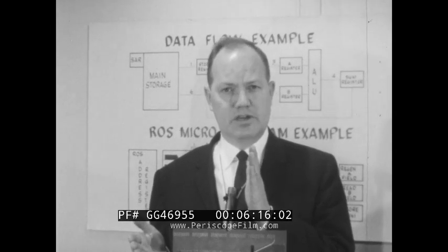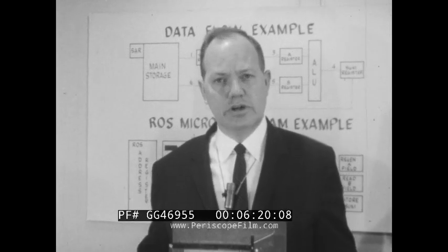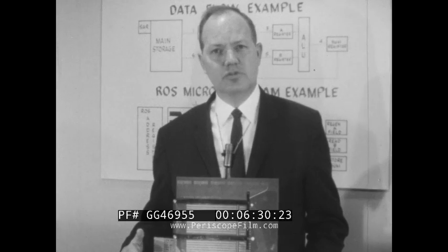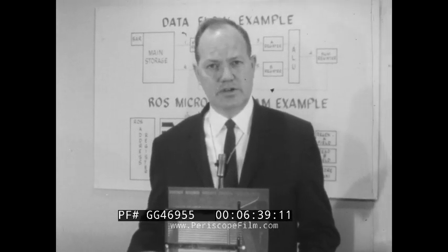If I perforate one of the plates or remove it, then I say I have a no bit, or a no capacitive pulse. Consequently, we are able to develop the 0-1 binary bit pattern required for the machine operation. The engineer determines what pattern he needs at a particular sequence in time of the machine operation and sets this up in the cards. That then becomes a permanent read-only storage that the machine will constantly utilize.